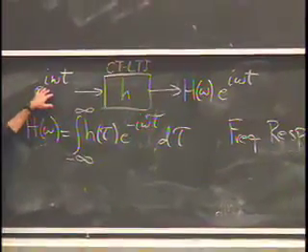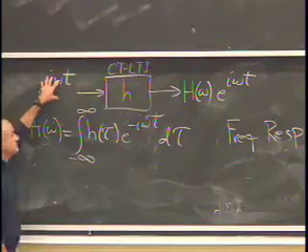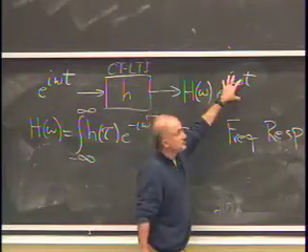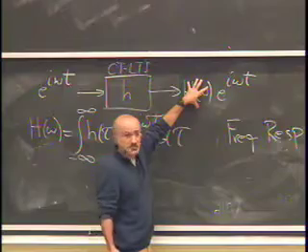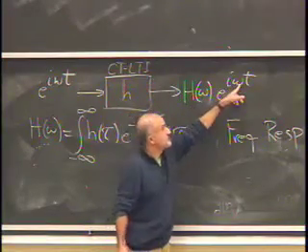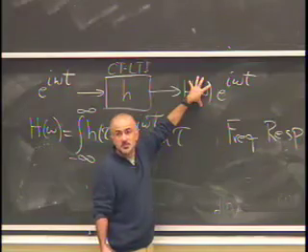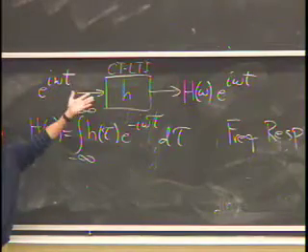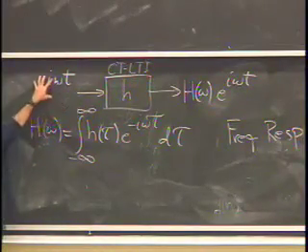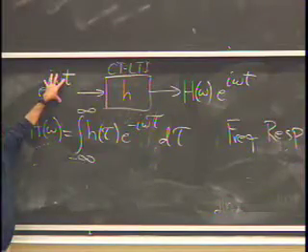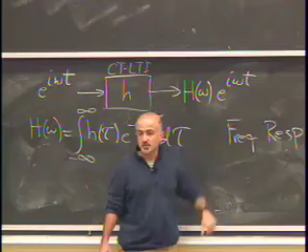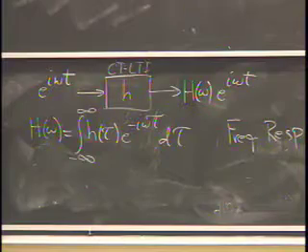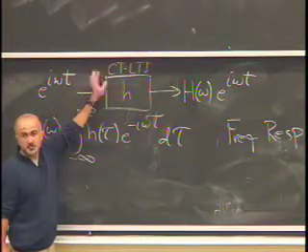So what this means is that complex exponentials are also eigenfunctions of continuous time LTI systems. When they go in, the same thing comes out, scaled. Now, it's possible for the filter to be such that for that particular frequency, this H of omega will be 0. That means it kills that particular frequency. So a particular frequency may go in but not come out. But you can't have a situation where a particular frequency is not present in the input, but suddenly it pops up in the output. That can't happen. And again, here you need linearity and time invariance for this property to hold.